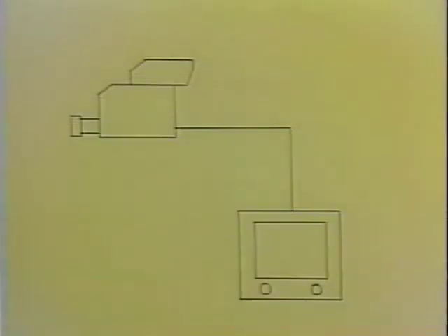A definite scanning pattern is desirable for two main reasons. It will ensure that the whole picture area is scanned and sections will not be left out, and it will ensure that any camera will work with any monitor. A definite scanning pattern has been chosen as the standard throughout the television industry, and as we shall see, it is the most important subject to the whole of a television system. Many scanning patterns can be used, and several have been tried. However, the pattern universally chosen is the same as we showed earlier.